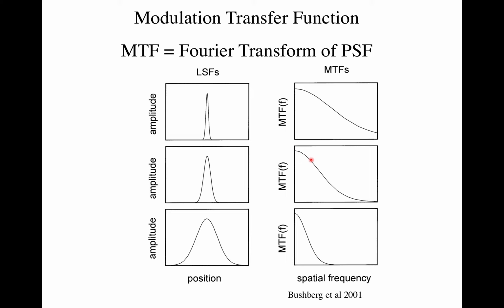Or you can say, well, how far out do I go in spatial frequency before I reach some critical cutoff that I'm going to call my cutoff. And so that's a little more variable. Companies usually don't pick the halfway point here to report their spatial resolution. They usually pick the point over here. They say, oh yeah, I'm at 1% at 2 cycles per millimeter or something. But realistically, everything's getting pretty tamped down by that frequency.